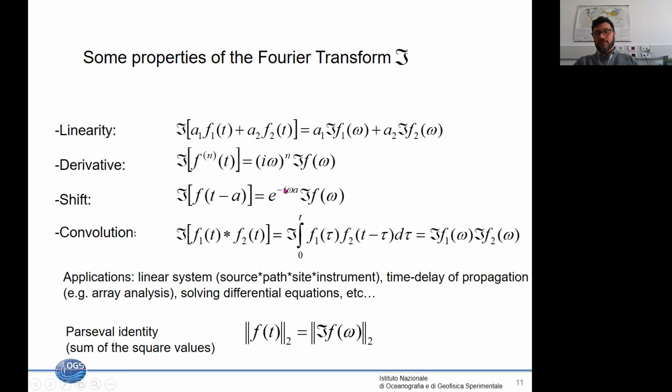So we see here that the time shift A corresponds to a phase difference in the original signal. Why a phase difference? Because if this is a cos term plus a sin term, the amplitude by which I multiply each frequency is equal to 1, since it is sin squared plus cos squared. But this term is adding a phase shift related to the ratio between the sin and the cos function.